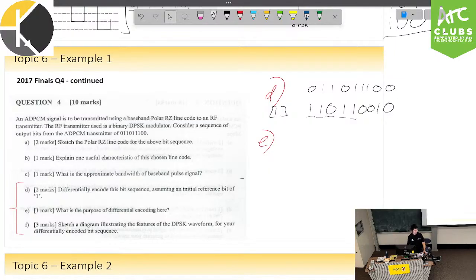Well, since you're looking at the change relative to your previous input, the phase difference is going to be relative to that previous input, right? Yes. So Jackson makes a fantastic point here. This is polar RZ line code, so since it is polar, based around 0, return to 0, a 0 is a low, then halfway, then a 1, and so forth.